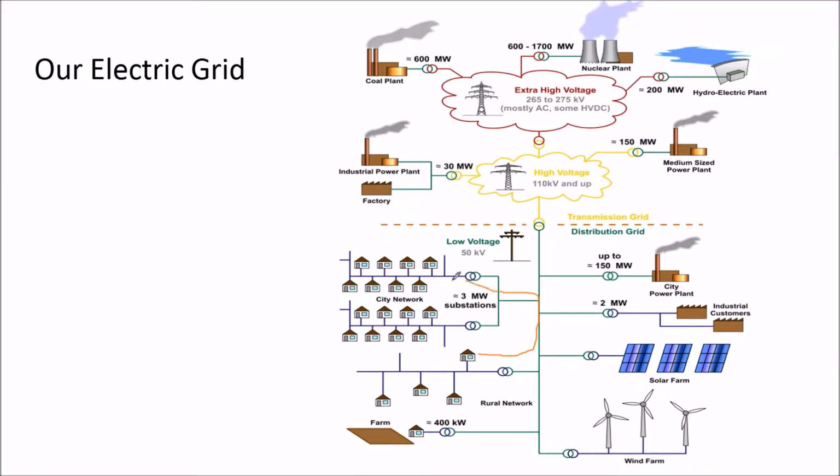Maybe this home down here is just trying to push power out to its neighbors, but you're still going through these little distribution circuit nodes that may not be capable of bidirectional electric flow. Normally, when solar is 0.1% of the grid, it's not a problem because your electricity just goes from your house into your next door neighbors, and it never makes it to these distribution circuit transformers.